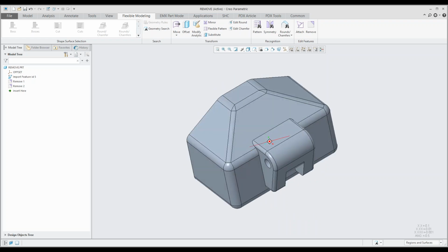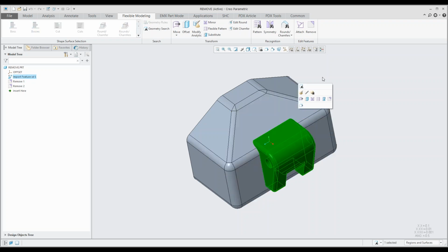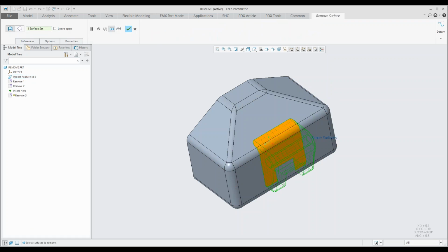And the second thing I want to show you is, let's say we've got a scenario where we want to remove geometry, but we still want to be able to see it. So you can sort of detach it from the solid geometry. So let's pick that and let's use the boss, and I'm going to say remove, but in this case I'm going to say keep removed surfaces.